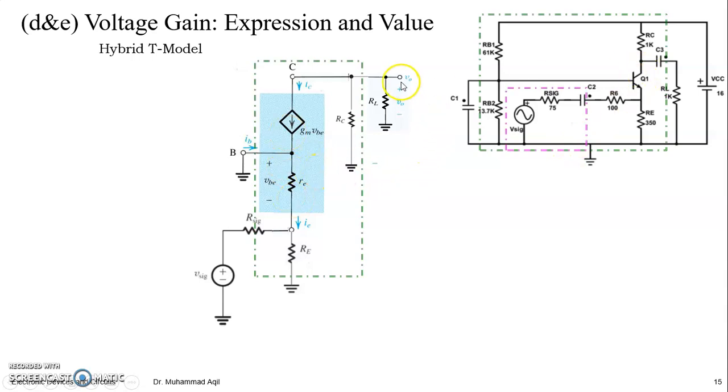Here the base AC equivalent circuit of this circuit is this one, and its stage is bounded with these dashed lines. Part of this resistance is here because we have R6 and R signal, combined to have R signal prime, right?